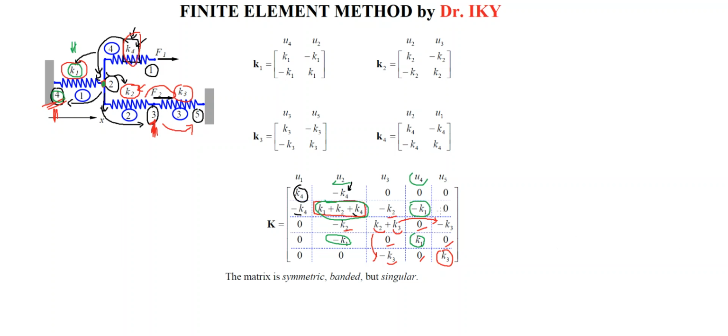They are going to create different matrix systems. You have to consider all of these for the parallel and serial connections of a linear spring finite element. So this is the whole system definition for stiffness matrix, or let me say matrix of the stiffness after applying the superposition method. And you have already know that this matrix should be symmetric, which can be understood from here. If you draw line here like this.